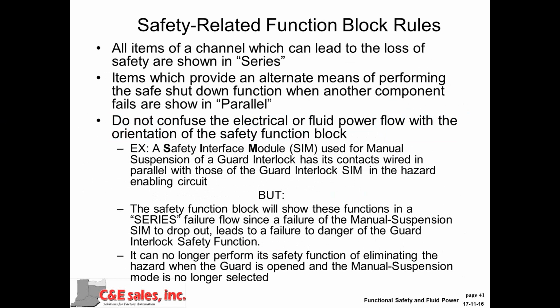However, in the fault diagram, the safety-related function block diagram, I would show them in series because a failure of the bypassing or muting function, if it fails to release that function, then I would not have any monitoring of the door. So a failure of that device to drop its muting or suspension function is a failure to danger.